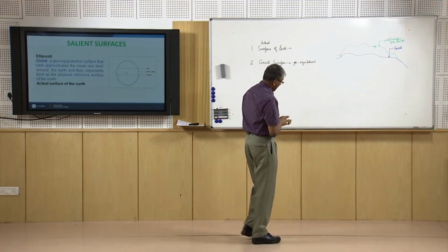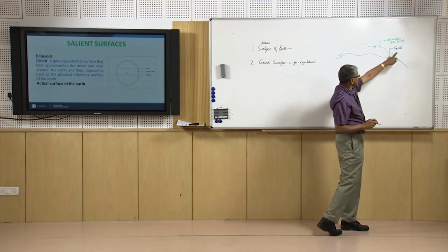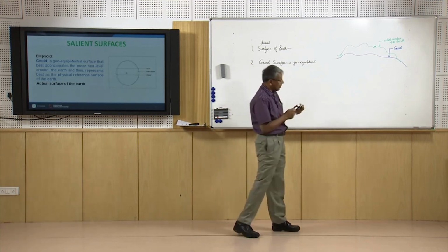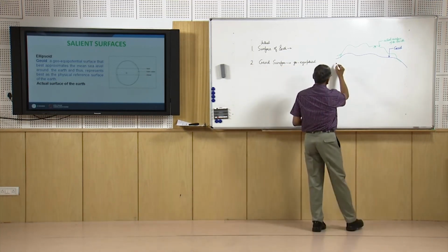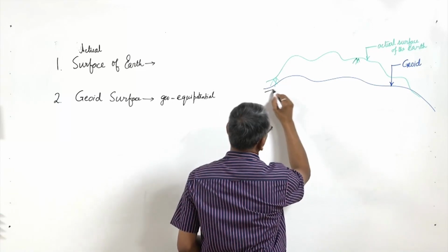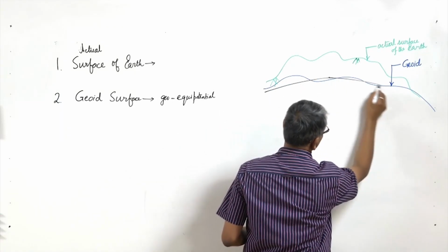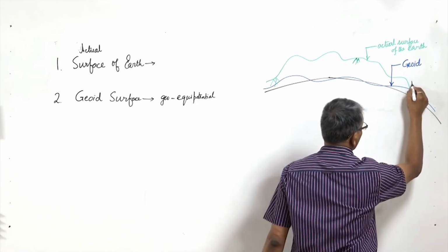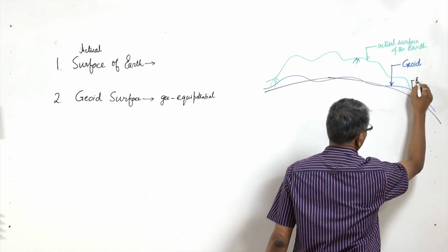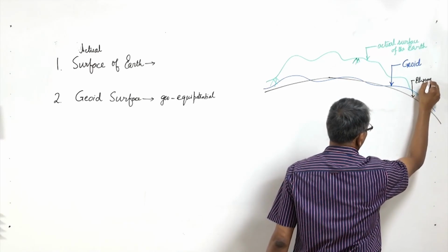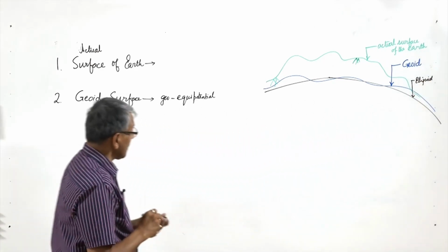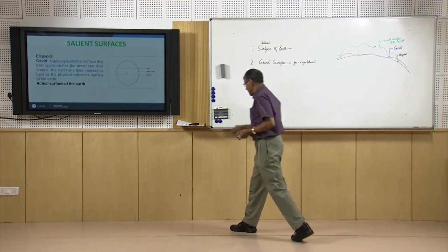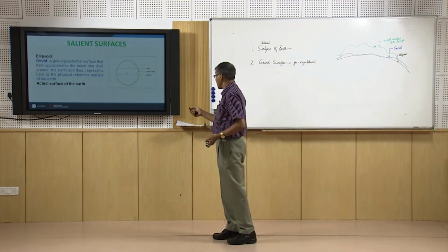And finally another, but this is also very turbulent in nature, so it is very difficult to develop a model or measurement on it. So geodetists had defined another surface, that is called ellipsoidal surface, which is quite regular in nature. Now, if we see this in terms of the whole earth, it may be shown like this figure.